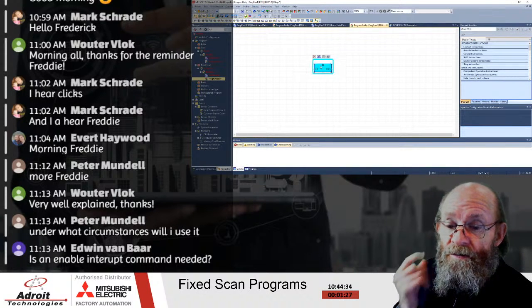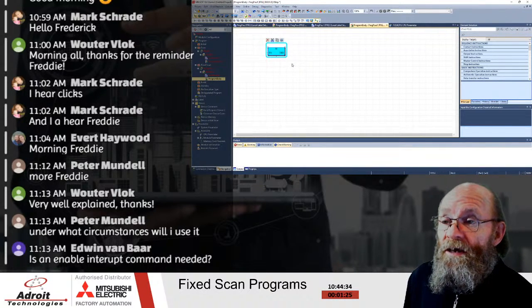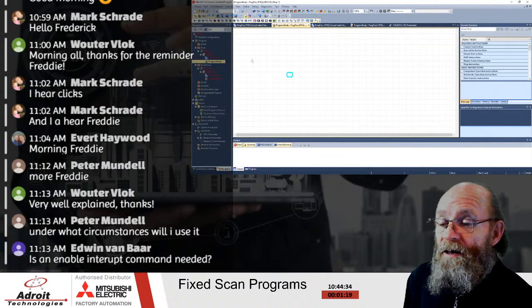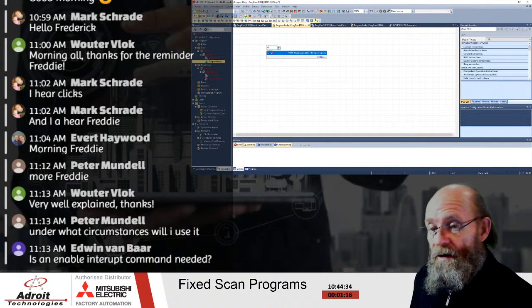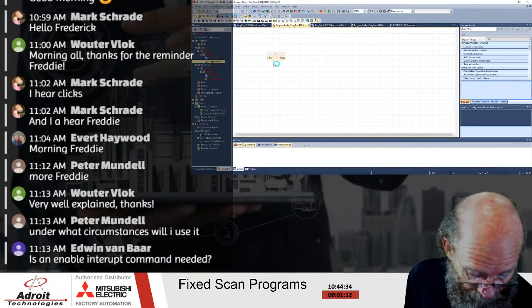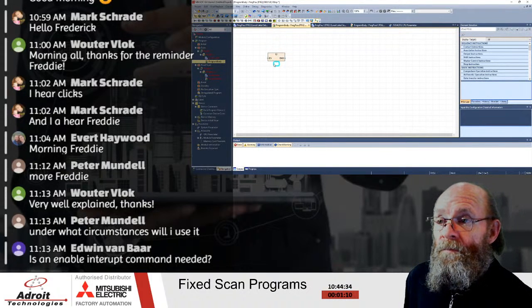So you would do that in your main program. When your main program runs, your first entry would be the enable interrupt block. Otherwise, interrupts will not run on the PLC. Okay. Thank you very much for that, Edwin.